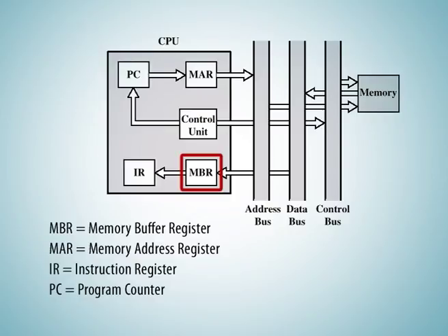The third important register which is involved in the fetch cycle is a program counter register, called PC in short. The program counter holds the next instruction to be executed. Fourth register involved is the instruction register, which is called IR in short. It holds the last instruction fetched.